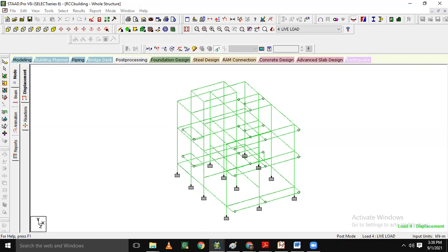To easily understand the local axis, use the right hand thumb rule in which your local x direction is shown by your index finger, local y direction shown by the thumb, and local z shown by the second finger.